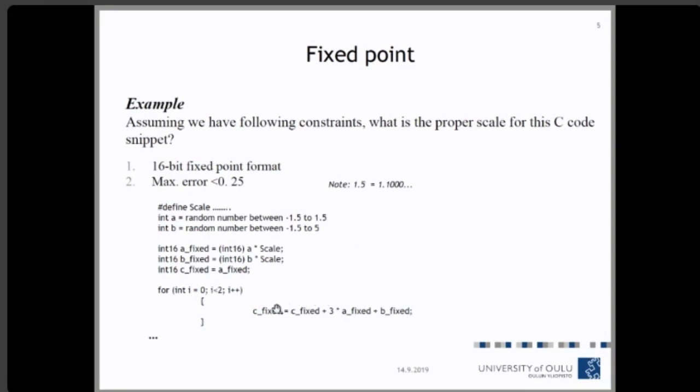We see if our scaling factor meets our demands or not, and then we adjust it so that we wouldn't have overflow, meaning the result would not be larger than 16 bits or larger than our dynamic range, and no underflow, meaning errors that would be larger than this.